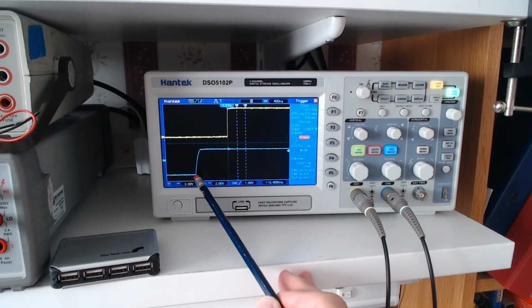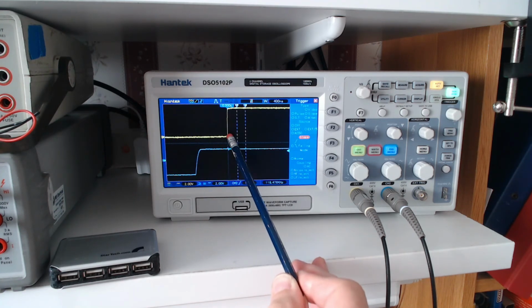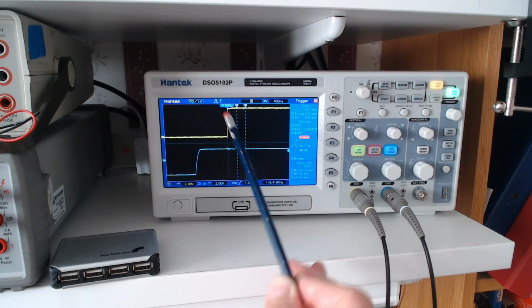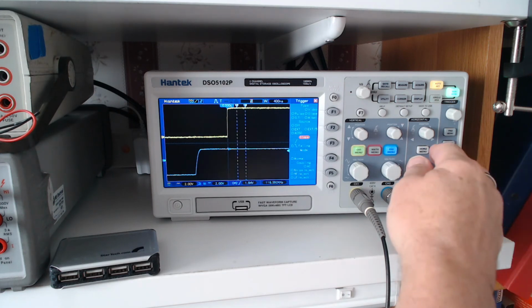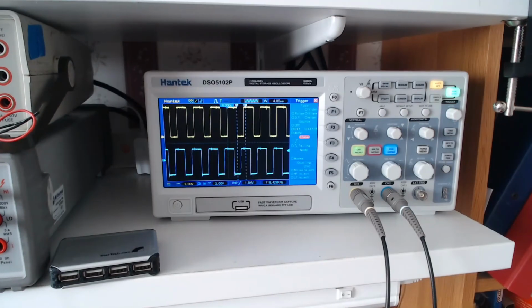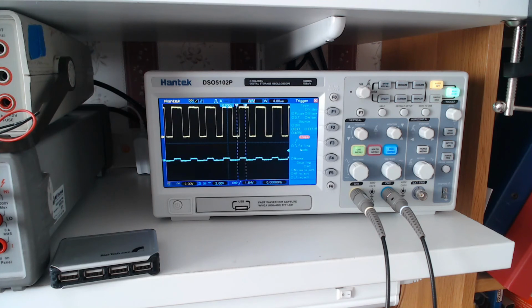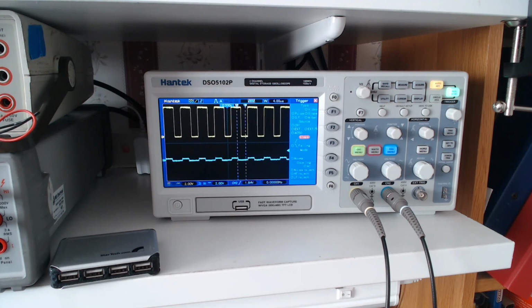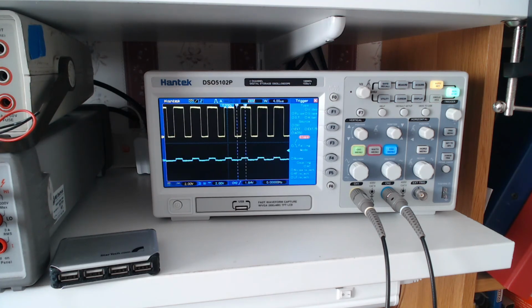I think if you speed it up, you will see that because it's a resistor pulling it up compared to an active device, we are seeing a difference in the rise times. And then thing to notice, if I take the resistor off the pin, it drops down considerably because it's no longer being pulled up.